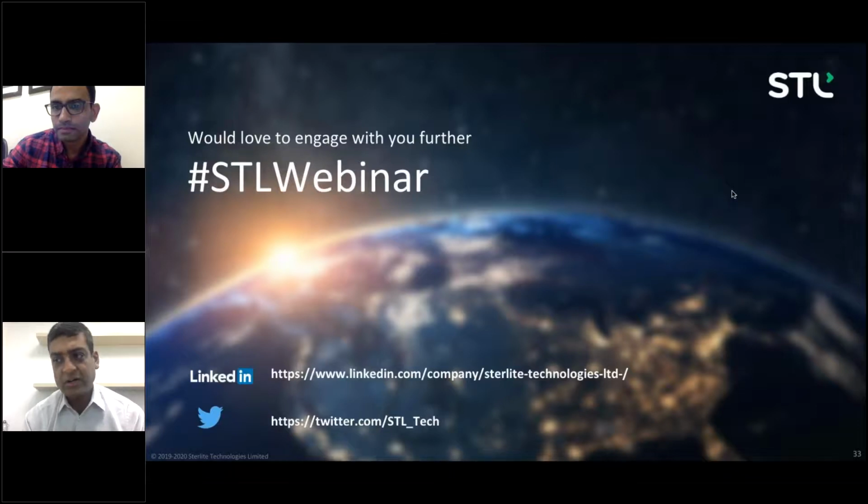The area that we have actually chosen to focus on is to make the life of a splicer as easy as possible when they're deploying a network. Right, so rather than focusing on the advances in splicing technology, which are going to be common to any fiber that we are using, let's talk about the aspects which cannot be fixed no matter how good your splicing is, which is basically the mode field diameter mismatch. Right, so the innovative approach that we have chosen to focus on is basically matching the mode field diameter and making sure that your